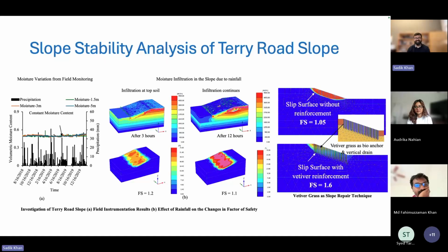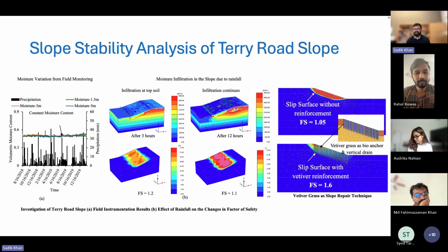That's another great question. Vetiver will help reduce the formation of the deep-seated failure. It will not mitigate the deep-seated failure because the root grows up to 10 to 12 feet, but it definitely helps to undo the soil moisture balance. So when it undoes the soil moisture balance, it reduces the amount of water infiltration into the slope, which basically goes down deeper and creates an imbalance. So reducing that moisture volume helps in terms of the deep-seated condition.